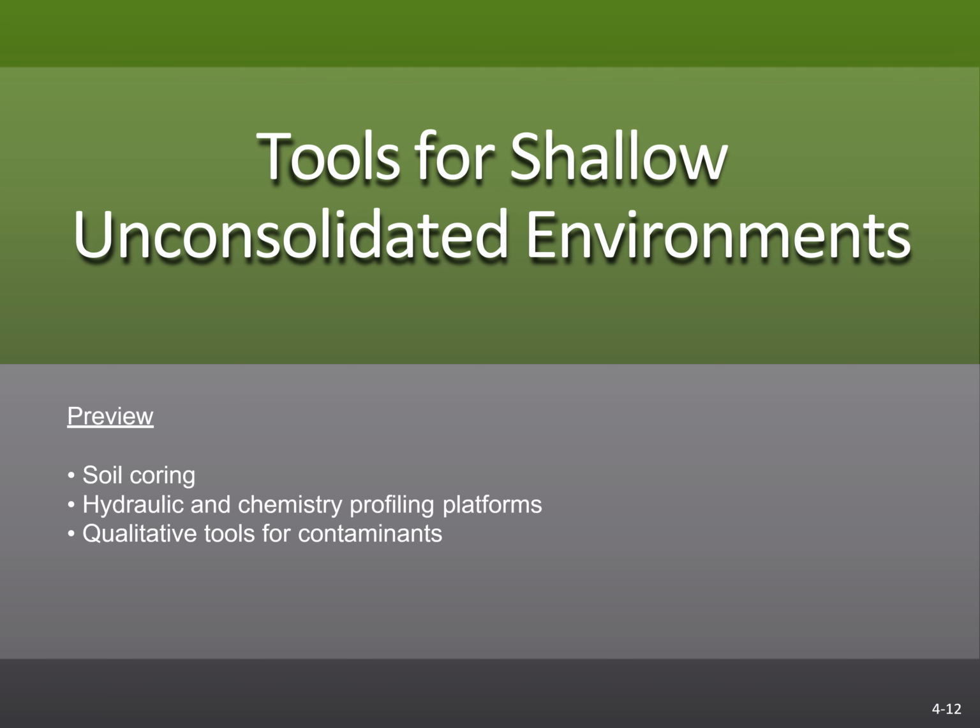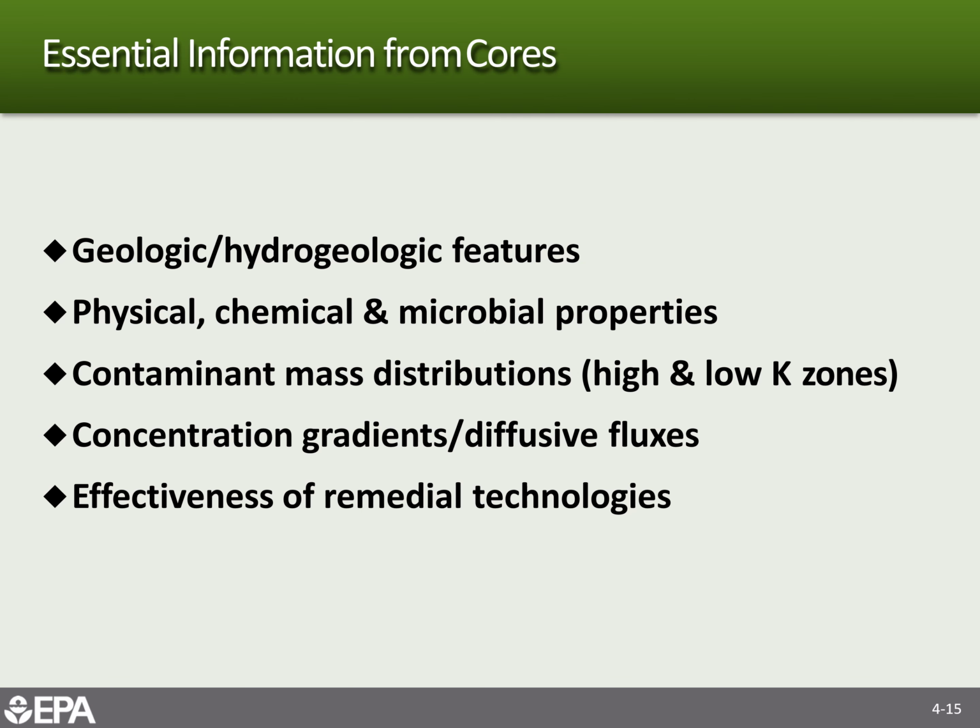So the first talk about the individual tools will be for shallow, unconsolidated environments, starting with soil coring. Essential information that you should receive from cores is both geologic and hydrogeologic features, a variety of properties depending on what your interests are at the site,